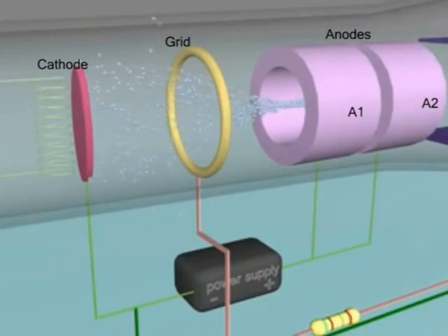The cathode is coated with oxides of thorium and strontium, preferred for their low work function. The anodes consist of cylinders and discs maintained at a high positive potential relative to the cathode. They therefore attract the emitted electrons and eventually direct them towards the screen.